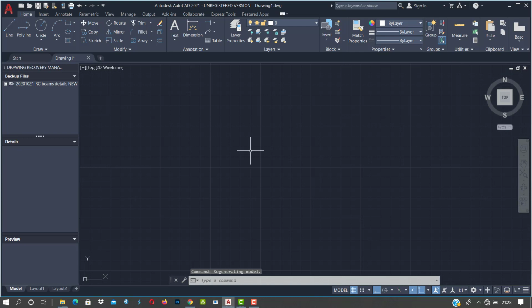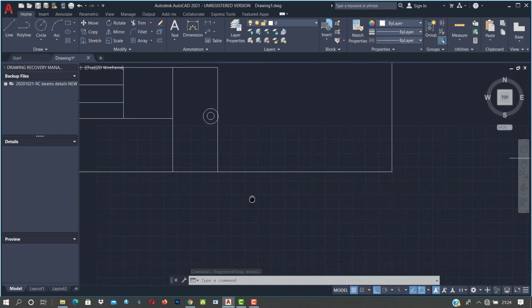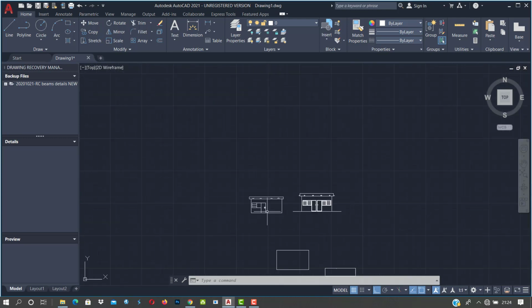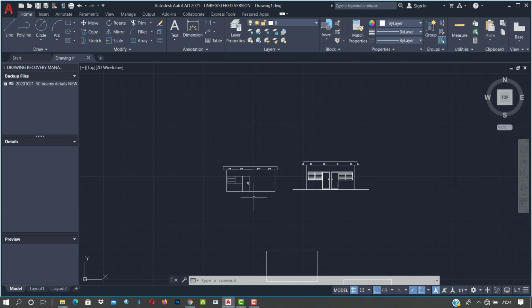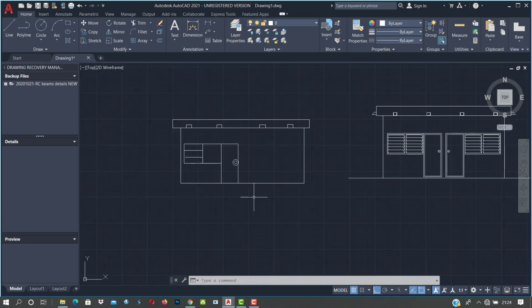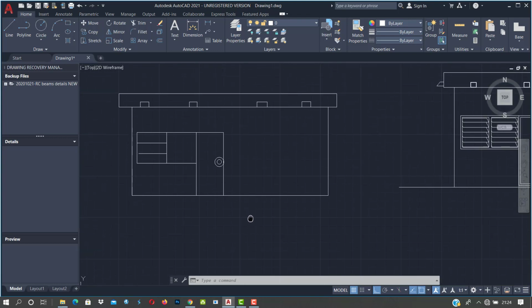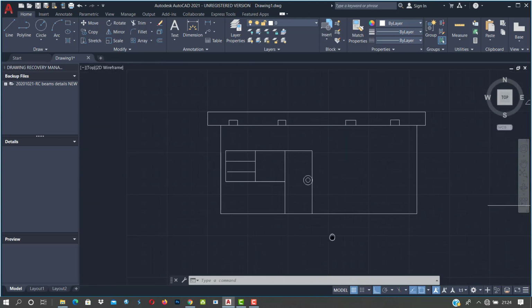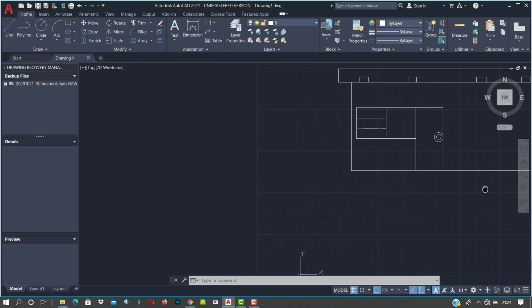You realize that your object is zooming in and out. You can also pan your object. You can put your finger on the same scroll button, but this time don't move it up and down, just click on it. You see a small hand on your screen. You can use it to pan around your objects.